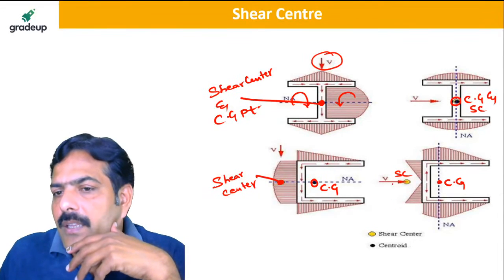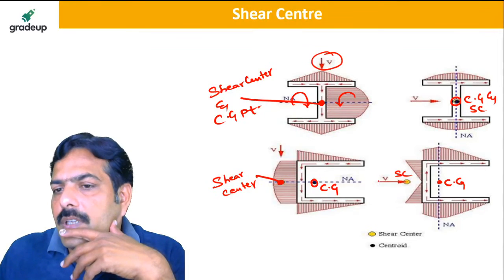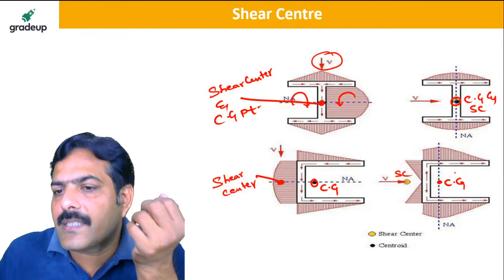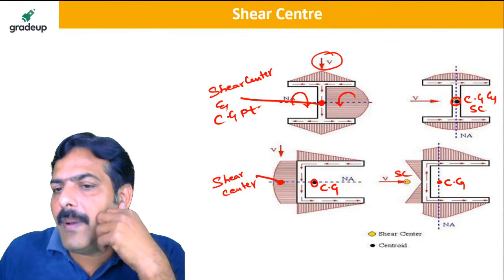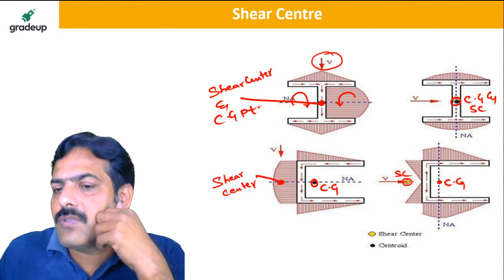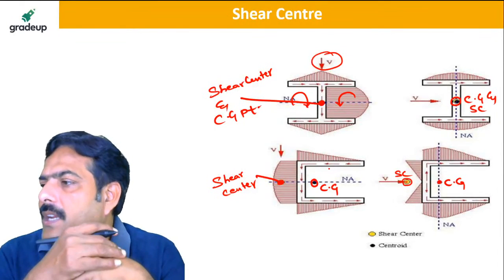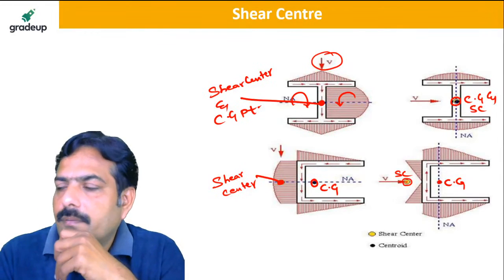In the fourth figure, there is a horizontal loading, my dear friends. When you see a horizontal loading, in this case you get a couple like this. Is it clear now? So in order to balance that, we apply the force at the center, which we call the shear center. This yellow color dot is called the shear center. Right? Very good.